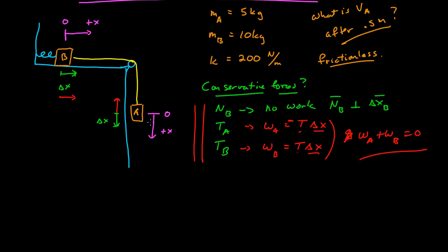So what does this give us for the forces then? Okay, so for B, what forces are doing work on the system? For B, that's just the spring force. And so the spring force, given the coordinate system of 0 at equilibrium, is negative k times x, whatever its displacement is. The force points in the direction toward equilibrium.